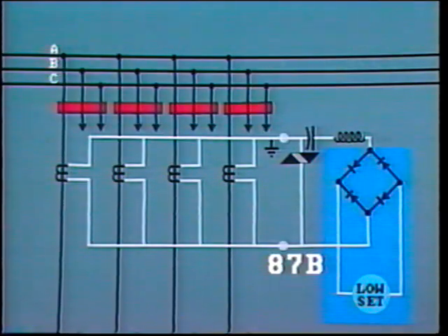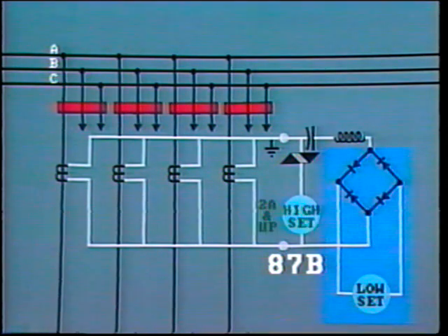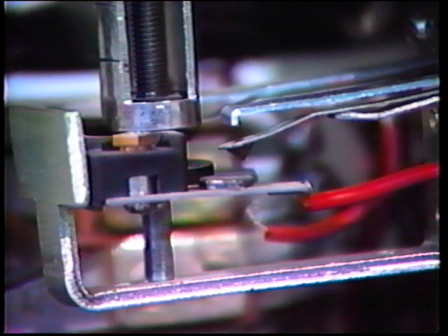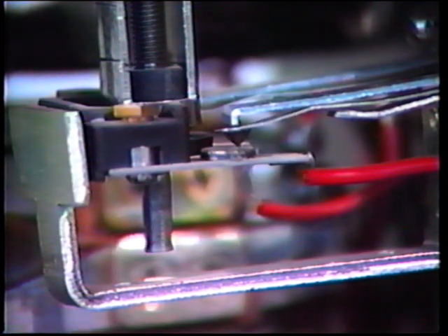Advantage is taken of this feature to provide further protection. An instantaneous overcurrent relay is installed in series with the varistor. This relay is set to operate instantaneously for very high levels of differential fault current. A range of pickup current settings are available from 2 amps and up. This is a plunger type relay which will trip within about 8 milliseconds, that is less than 1 cycle. This is extremely high-speed operation.